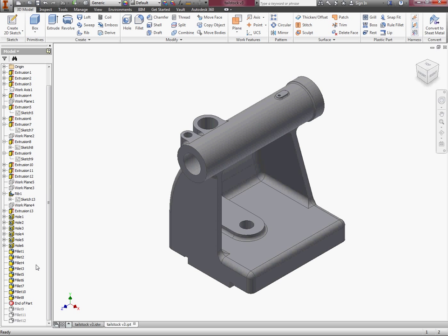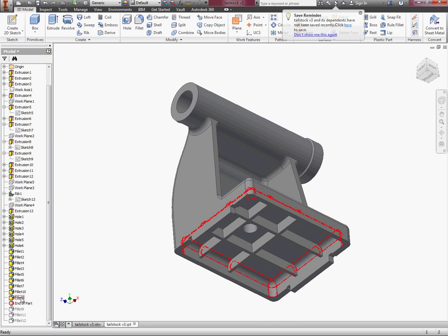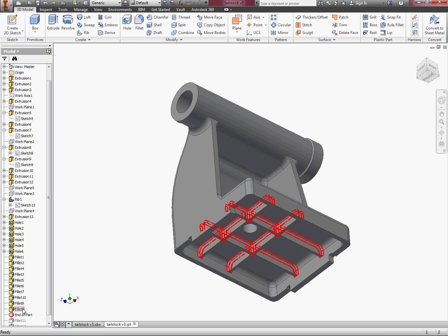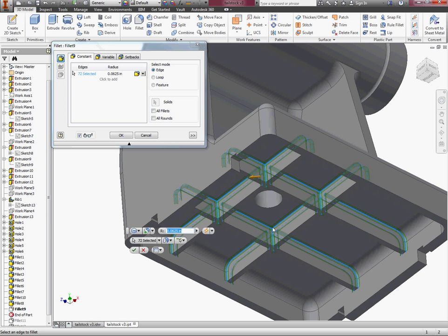And then we have the underside of the base. Down here, the roof. You're going to do the 4 edges of the roof and then the 2 vertical under there. Those are all 1/4 inch. And then all the ribs, they are 1/16 inch fillets. Along the ribs, the roof, where they join in between, all those edges, 1/16 of an inch.